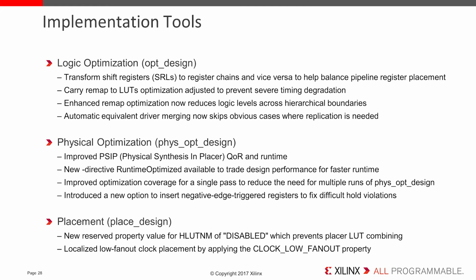There's a new directive, RuntimeOptimized, where Vivado trades some QoR for faster runtime. Overall, Vivado should cover all possible optimizations in a single pass such that successive looping is no longer required. There's also an advanced hold fixing option to insert negative edge triggered registers to fix hold violations.